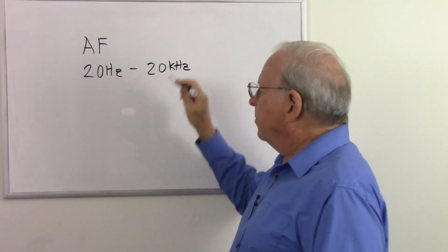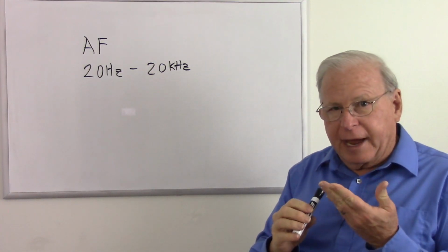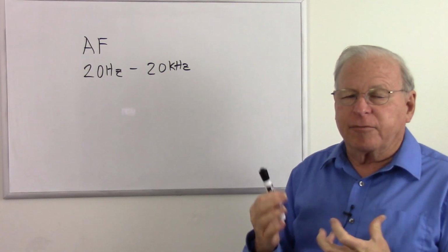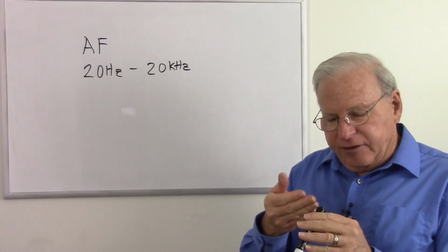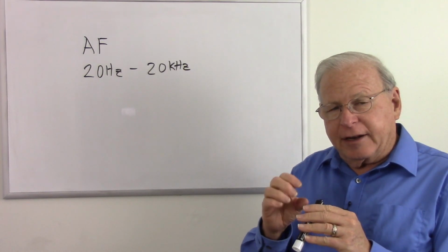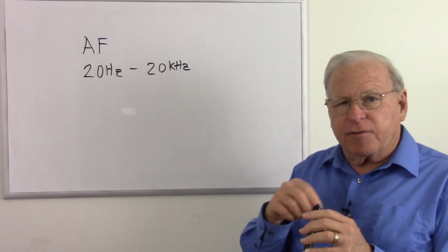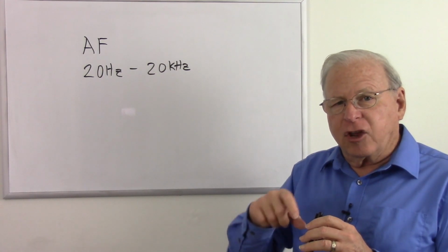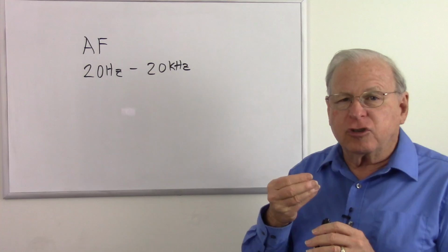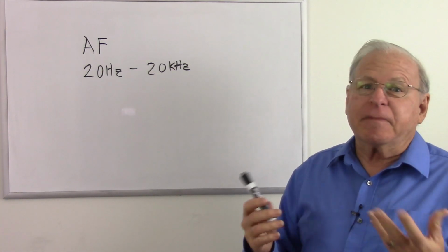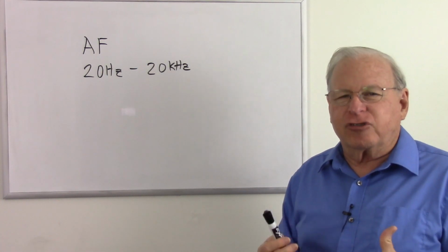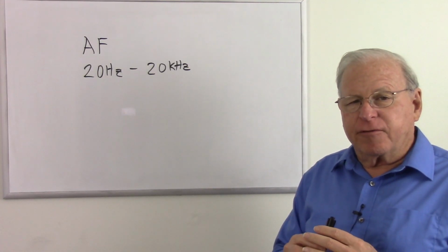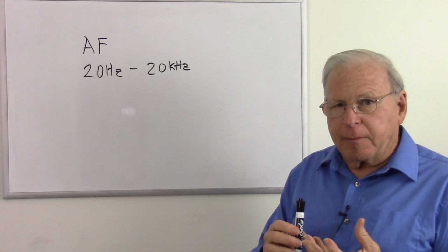And to finish my explanation about the vibrations in the microphone, I'm talking, producing a lot of different vibrations of all kinds of mixed frequencies, and that's causing that diaphragm to vibrate. That diaphragm in a dynamic microphone is going to have a coil of wire in a magnetic field, and that's going to cause a current that is proportional to that vibration to come out. Alexander Graham Bell called them voice-shaped currents. There are other types of microphones too, but let's just look at the dynamic microphone because that's the easiest to kind of wrap our minds around.